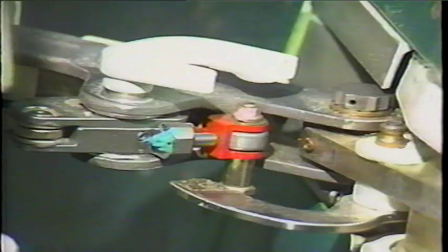Return the door to its fully closed and latched position. As the door closes, the fixed pin should cycle the trigger to the detached position. Open the door to expose the trigger assembly. Verify that the fixed pin on the door structure sequenced the trigger assembly fully back to the detached position. If the trigger assembly is not sequenced fully back to the detached position, determine if binding exists in the trigger housing assembly. It is possible that there may be binding at the trigger pivot point and/or at the spring cartridge pivot point. This binding could prevent the fixed pin from properly sequencing the trigger.